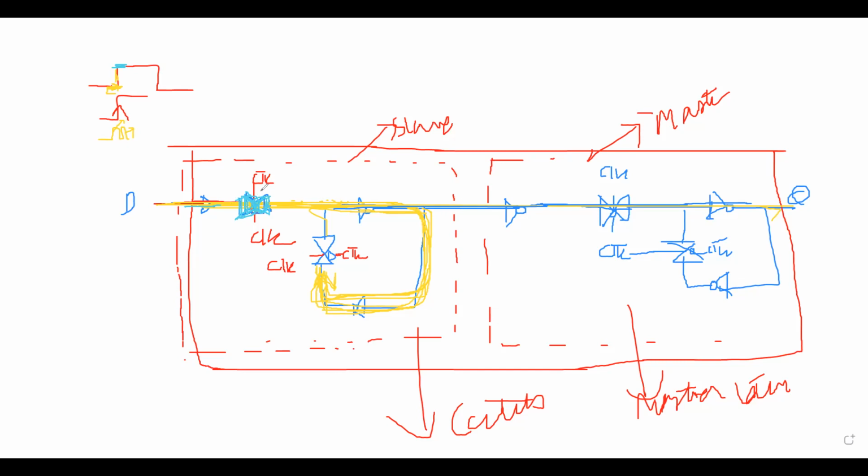That gate closure needs some time. Let's suppose the gate takes 5 nanoseconds. Up to 5 nanoseconds, we should not transfer data from here to here. That moment of time is the hold time. So hold time only depends on that transmission gate, right? Yeah, just that one.